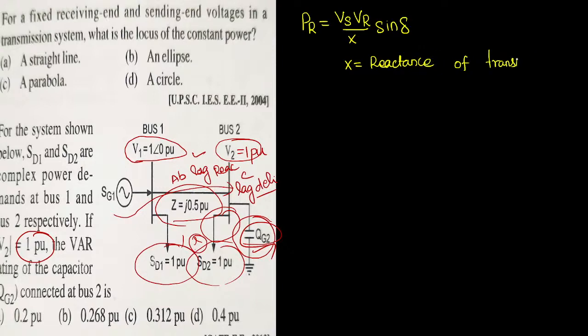That is very important. Okay sir, that is over. First case, what is the formula to obtain the reactive power? I hope you all remember: sending end voltage times receiving end voltage divided by reactance X times cos delta, minus receiving end voltage VR squared divided by X.